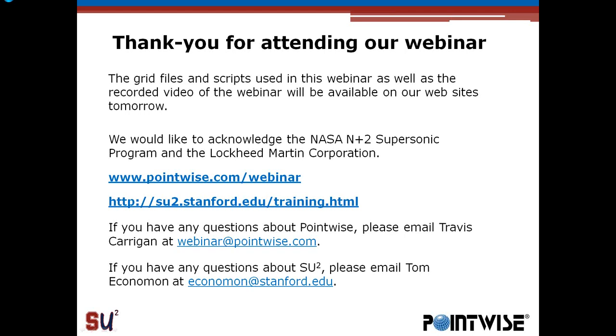So I hope that is answering this question. We never operate directly with the surface sensitivities during the design process. We always project that into a design space of our FFD control points, for instance, and then use the gradient that we receive from that. So this makes sure that we have a well-behaved flow solution and gradient for the optimization.